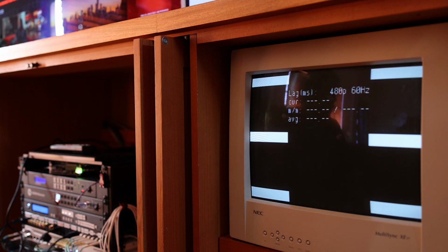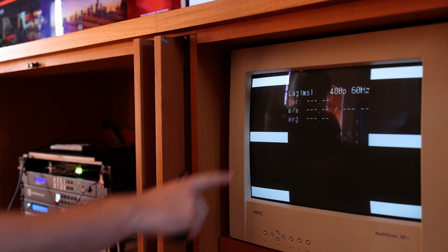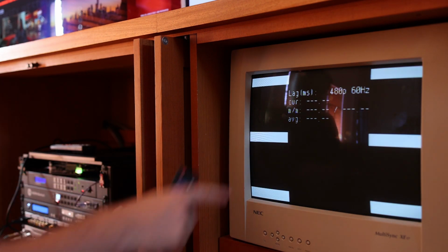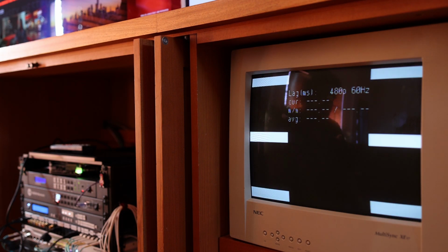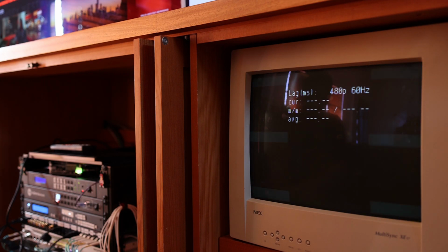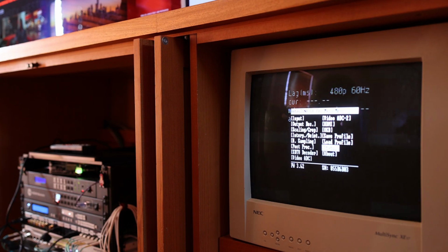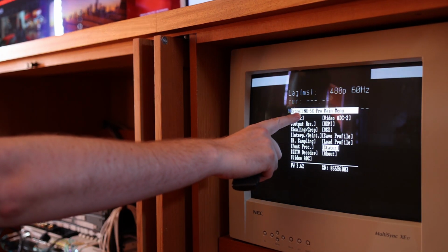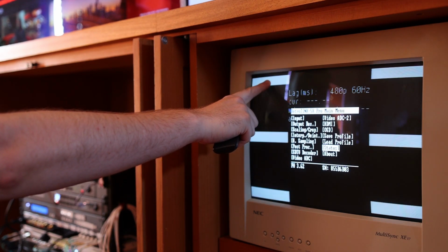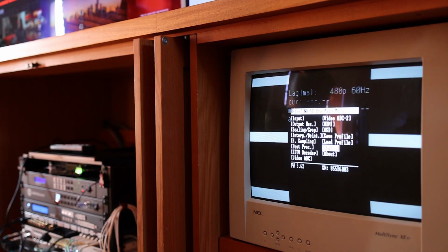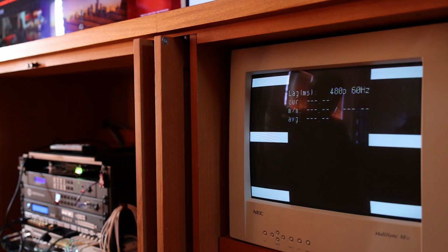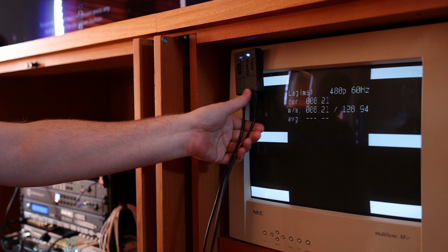What's really important to note, first off, is how much dimmer this signal actually is compared to what it should be. The voltage levels coming out of the SCART adapter seem to be much lower than they should be. For instance, if I bring up the RetroTink menu, you can clearly see the brightness of the RetroTink menu compared to what is white, or max brightness, coming off of the SCART signal there. So now let's measure some of this latency on this.